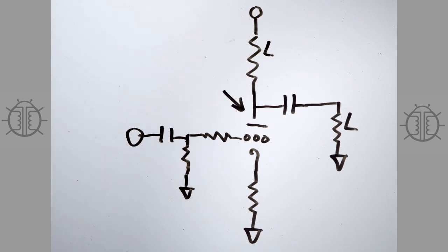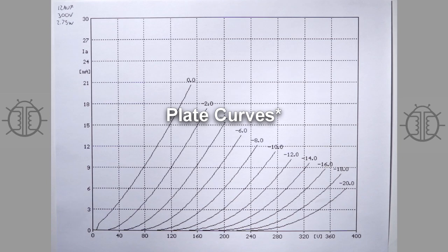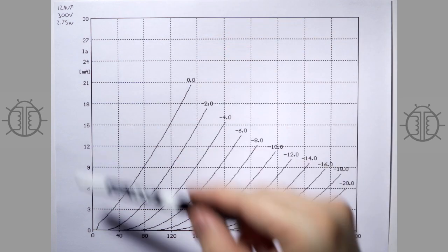You've probably seen these load lines in the data sheets of the various tubes you've looked at, and they might look a little mysterious, but they've designed them to be very easy to use and helpful. There's a lot of data in here, as you're going to see. The reason they include these is because data sheets give a bunch of specs, like maximum ratings, maximum current, and an average operating point, but those are snapshots of the bigger picture of what the tube can do. This is a much more complete picture.